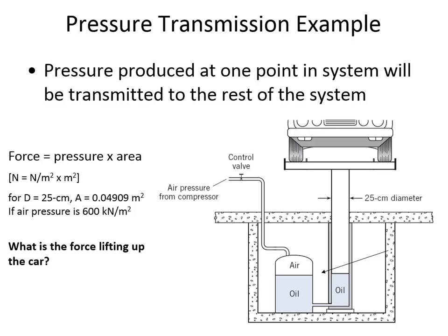What's that? The oil's incompressible. Okay, that is true. But why does that make the cylinder rise? The air is less dense than the hydraulic oil? Well, the air, yeah, that's also true. The air is less dense. Let me draw what it's going to look like when we add more air to there and it displaces the oil.